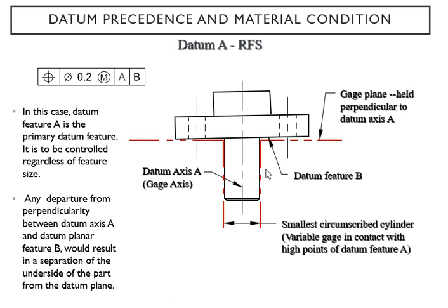You can see the datum A, regardless of feature size, and we have another datum which is B, right here, yeah. And of course, you're still dealing with the maximum material condition, okay. So your datum A is right here. That's your axis, and that's your primary datum because it said so here in the control frame.